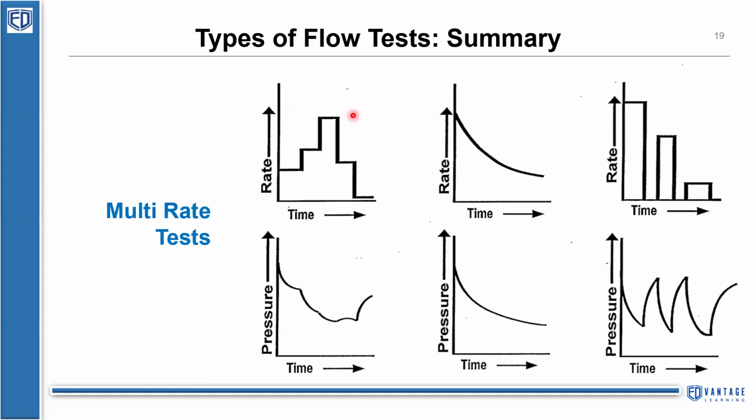Yes, that's right. We try to alter the choke size. That is also called as bean size. So we increase the choke size. That choke size generally comes in 1 upon 64 millimeter. So we choose 2 choke size, 4 choke size, 6 choke size, 8 choke size. The moment we increase choke size, your production rate improves or multiplies, and your pressure drop also multiplies. So that is something important to understand.